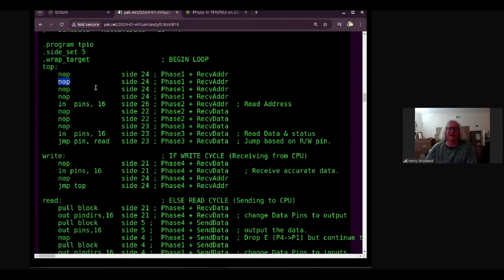I just had a different divisor. I started out dividing the 133 megahertz clock by 8. And then I started to say, I've got instructions to spare. What if I have that speed? All right, I double the speed, so I'm only dividing by 4. And then I look to see if it breaks. And if it breaks, I try inserting some no-ops.